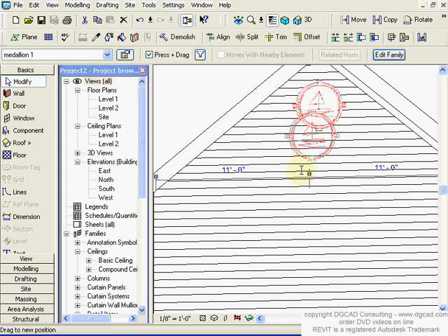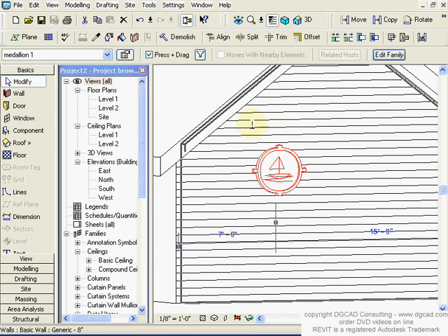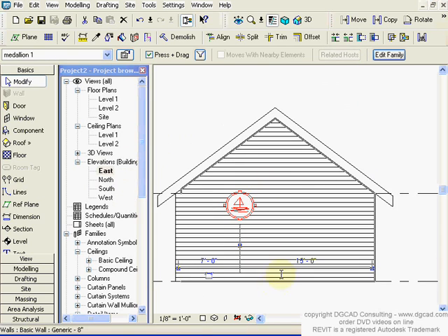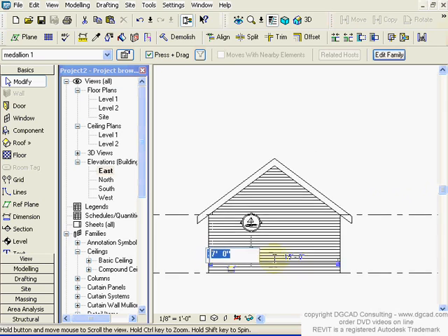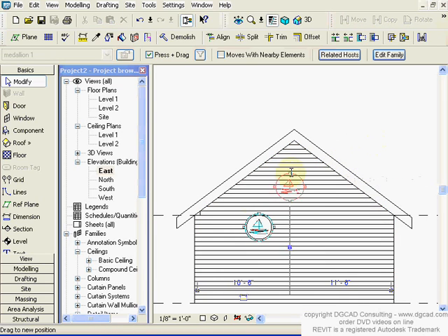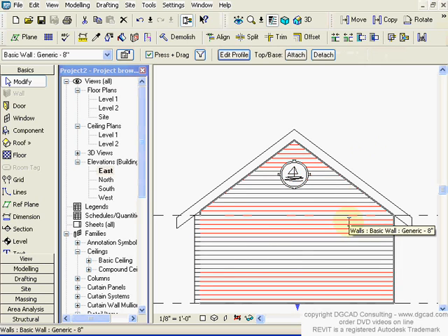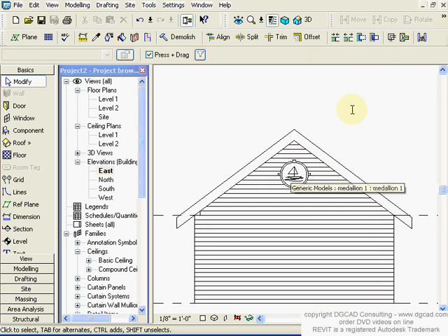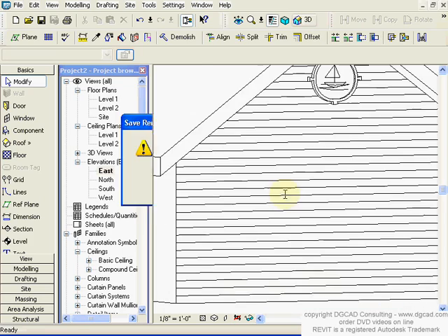This is an example of one of those that's in place, and I can click on that and move it around wherever I want. It doesn't matter which view I look from. I can look from the east view, pick this, and change my number to set the location of that. I can again click anywhere I want and place it. Again, if I delete the wall, the object will delete because it's being hosted by it.